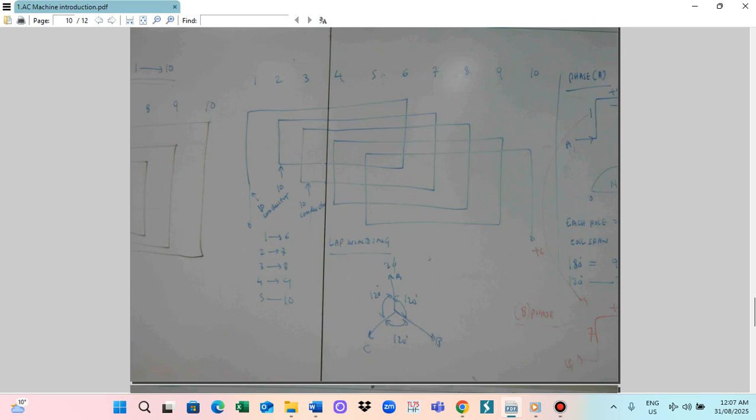It is not only one wire; there will be a bigger wire, many wires, to produce the appropriate magnetic flux. So every coil must have the same number of turns. Otherwise, if the first coil has 10 turns, the second 20 turns, and the third 15 turns, then after you finish, your motor will not run properly. There will be fluctuation like this.